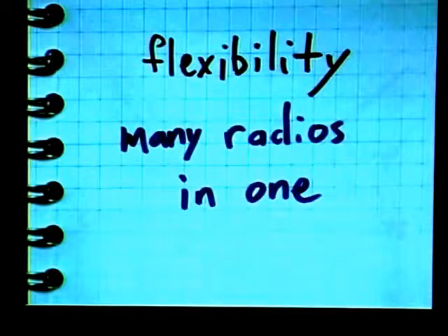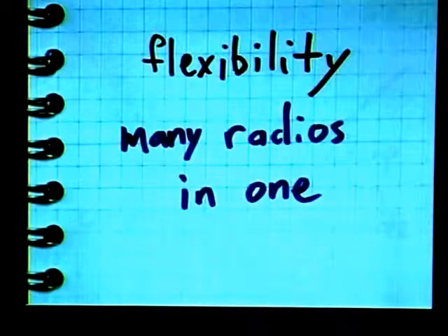You could, in fact, use a single radio to receive multiple different bands of signals, TV, Bluetooth, across various different spectrum, and demodulate it all with one radio simultaneously. You could also, by using that technique, consolidate a bunch of different radios, like the radios that we have in our cell phones, into a single radio. You could take Bluetooth and Wi-Fi and GPS and NFC and cellular and bring them all into a single piece of hardware that just runs software on the resulting sample stream in order to decode or encode whatever signals you need to transmit.